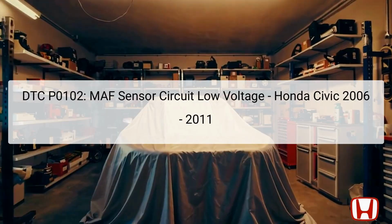Welcome to the diagnostic presentation for DTC P0102 related to the MAF sensor circuit low voltage for the Honda Civic models from 2006 to 2011. The DTC, or Diagnostic Trouble Code, indicates a problem with the mass airflow MAF sensor, which is crucial for measuring the amount of air entering the engine. The information we'll cover today will help you accurately diagnose and resolve this issue.